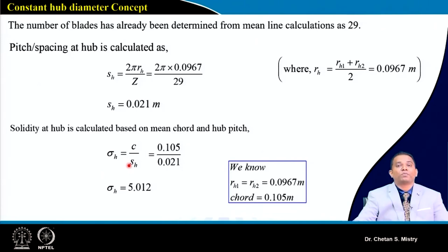Now at the same time, suppose we have exhaust fans. For those exhaust fans, many times for design they take the chord at the tip region to be large. So those are all different design philosophies, and as I told, with whatever numbers you are playing with and ultimately what you get in the sense of your final shape of the blade, just go with your computational tool and try to achieve the expected performance.